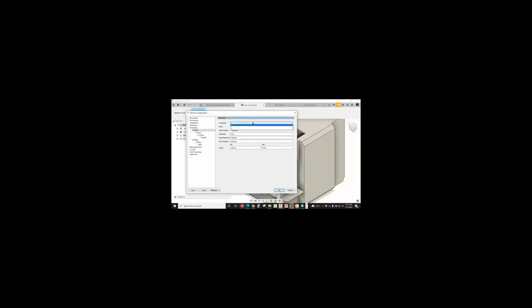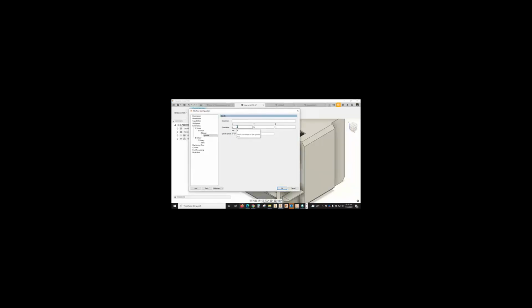If our linear axis, we want our main linear axis, we can change right here. Y linear, Z linear, spindle. Okay, so what's our max spindle speed? We can get a lot of this information from the supplier as well. And anytime we want to activate an orientation on our machine, we can use that with zeros and ones right here. So one being the activated spindle axis. Okay, so that being Z.